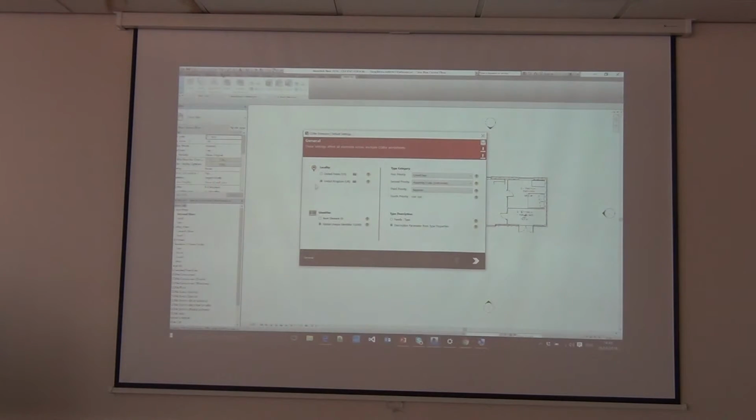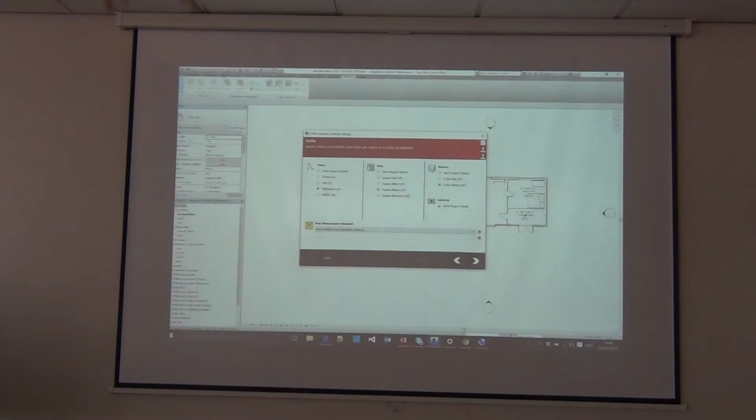How do I want to identify my objects? Do I want to use the Revit ID or a global ID? What classification systems do I want to use? And of course these are all American, none of the British ones are in there, which is really a pain. And actually to get these to be the British ones is not straightforward, but for another lecture. Okay. And then it's saying what units, that's really important for Cobie. So it's setting up that I'm in millimetres, I want things in square metres, and I want things in cubic metres.